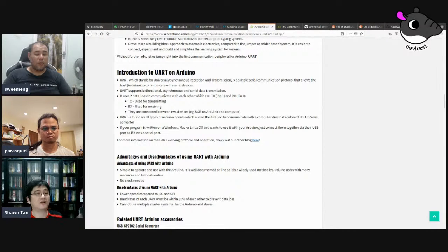Because there is no clock. The clock is not on the line. So you don't know when the signal is right or wrong. You sample according to your own internal clock. And the internal clock has to be in sync with the other guy's internal clock. I hope that made the thing clear.